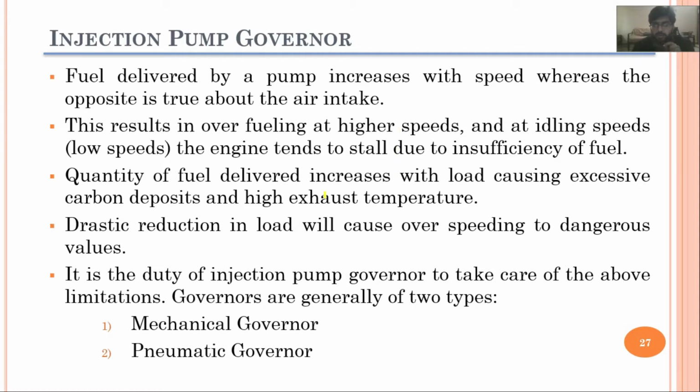The quantity of fuel delivered increases with the load, causing excessive carbon deposits. That's the environmental effect I was mentioning: at higher loads more fuel is injected into the combustion chamber, which can result in incomplete combustion, thus giving us excessive carbon deposits and high exhaust temperatures as well.